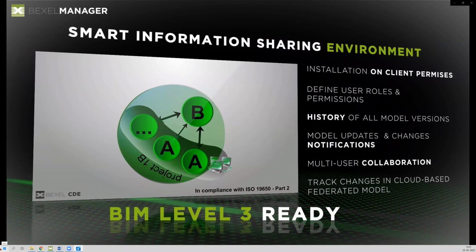And as I said, we also can create smart selection sets, which are created by defining certain rules, and the elements have to apply to those rules to be a part of this certain smart selection set. And if you update your model and new elements are added, they will be automatically divided or placed in certain selection sets if they apply to all rules. So this is the main difference between creating a regular selection set or a smart selection set.